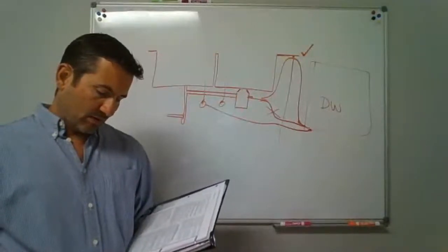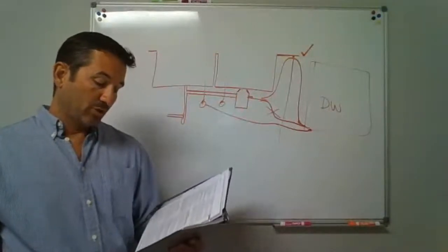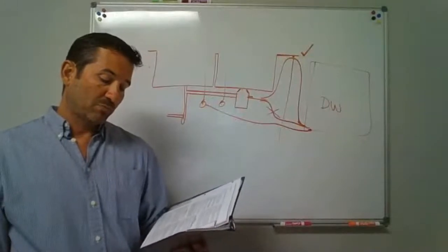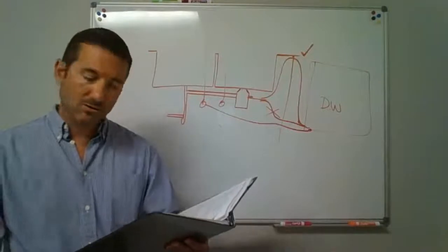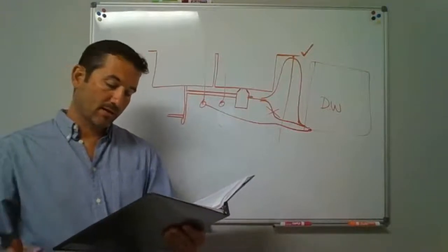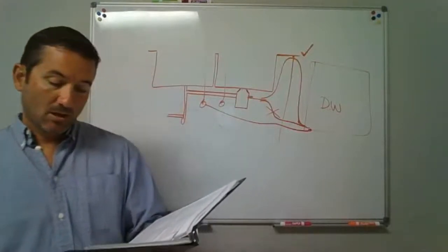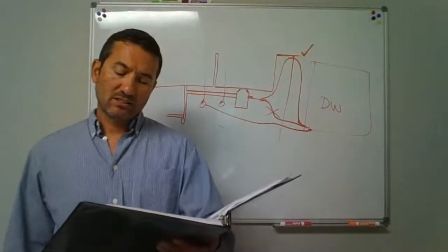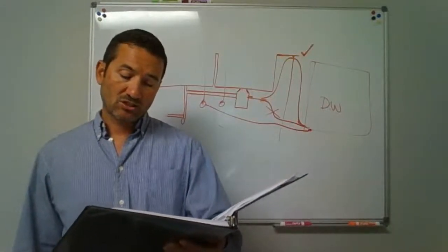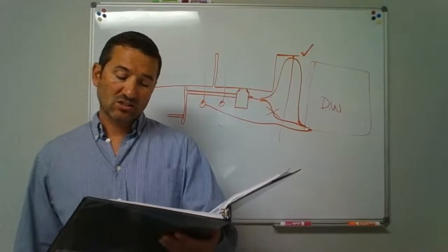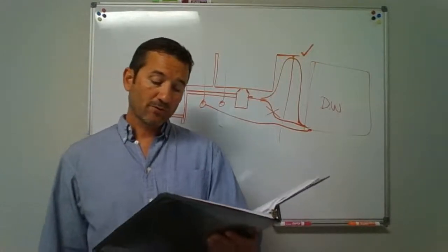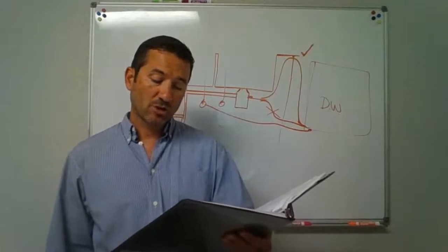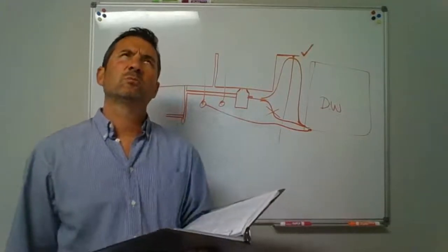Let's go down to the installation 802.2. Indirect waste piping shall discharge through an air gap or air break into a waste receptor. You keep hearing those terms. Air through an air break, air gap to a waste receptor. Waste receptors should be trapped and vented and shall connect to the building drainage system. Indirect waste piping that exceeds 30 inches in developed length measured horizontally or 54 inches in total developed length shall be trapped. And say, ooh, developed length.